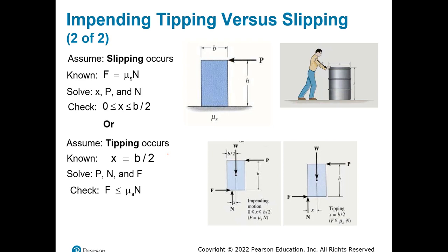When sliding occurs, and that's what you will be doing all the time, your maximum condition, when you're designing, you have to design based on maximum or critical conditions. Your critical condition will be that the frictional force is reaching its maximum. But for that to happen, the normal has to be between the center and the edge of the object, okay? If it's between 0 and b divided by 2, being b obviously from one face to the other, if that's the case, then boom, slipping occurs.